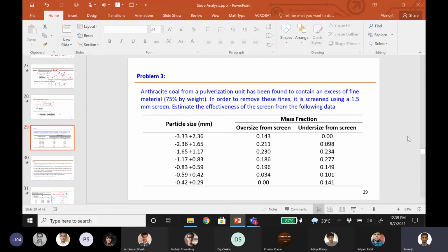But in real life, in the feed itself, you don't know. That is also you are using a sieve. That's why we do all this analysis, and sometimes the cutoff number that you want to use for separating the particles may not be standard with the sieves. So you have to go for all these plots and all this data to find out the exact point. Okay, sir. Yeah.